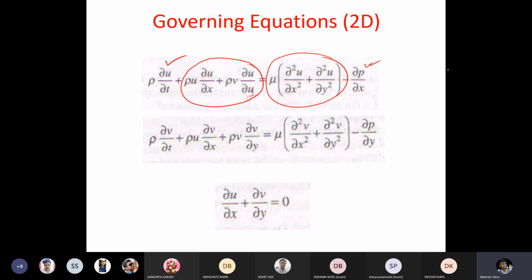If you recall, we first wanted to discretize the diffusive part in the form of the one-dimensional steady state heat conduction equation. We have seen that there are many discretization techniques, either finite volume or finite difference. In finite difference we can have forward difference, backward difference, central difference, etc., and this part can be discretized.